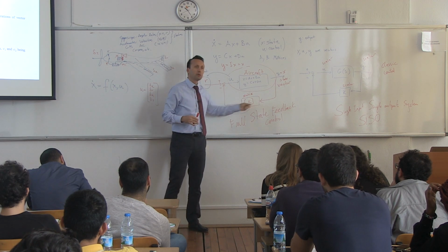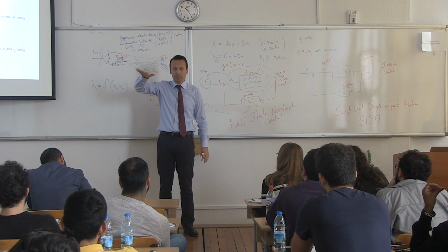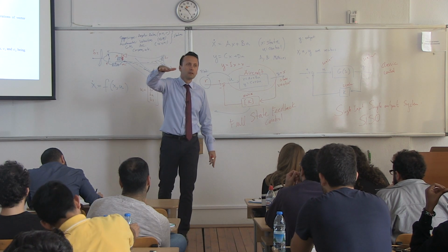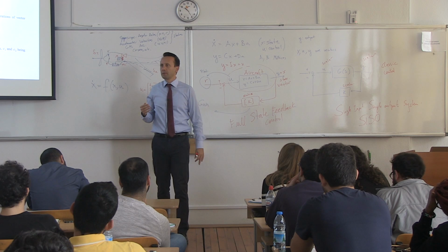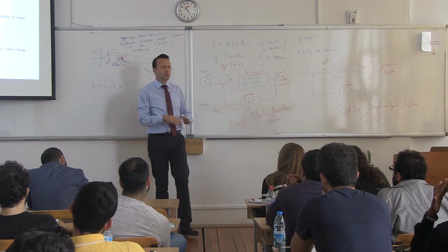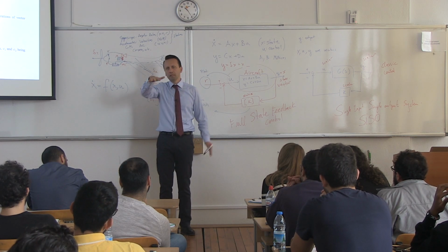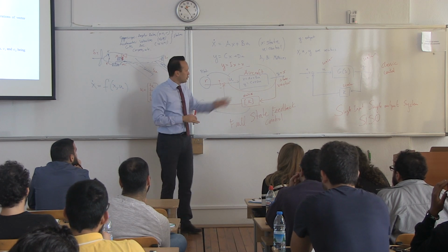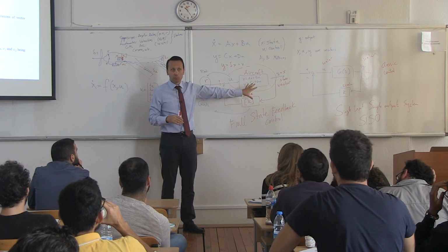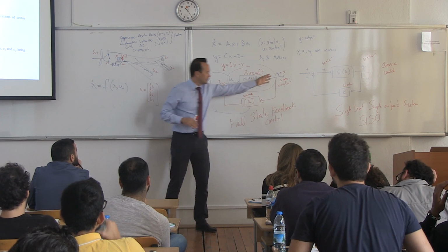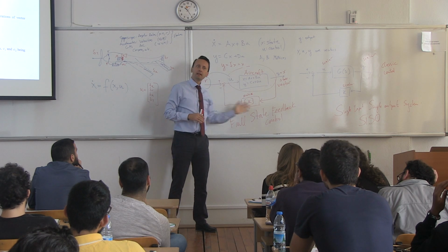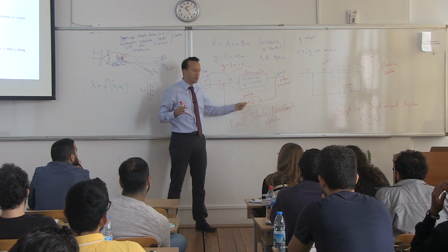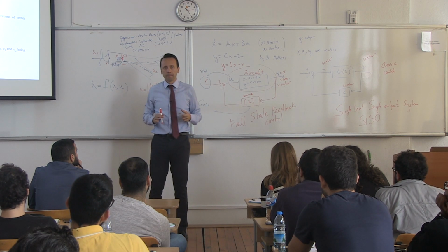The K matrix will look quite different. At hover, the helicopter is unstable. At 70, 80 knots, fast forward flight, you are becoming stable. So obviously the controller will do a lot of work in hover and probably less work at 70, 80, 90 knots. So therefore the controller will look very different. The architecture probably looks very similar though. This architecture, the idea, the methods, they will all look very similar. What's going to really change is this one. Okay?